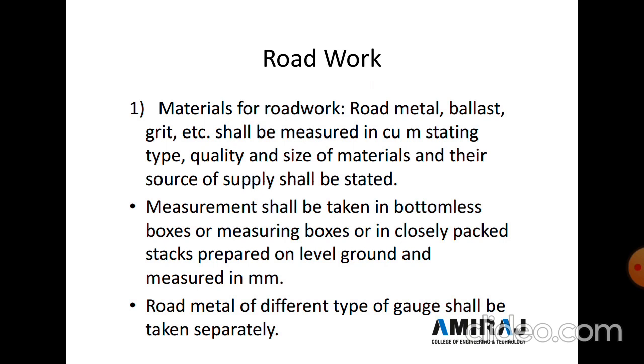Now the next topic we discuss in modes of measurement is road work. Materials for road work, such as road metal, ballast, grit, etc. shall be measured in cubic meters. The type, quality and size of the material and their source of supply shall be stated, and the measurement shall be taken in a bottomless box or a measuring box or in closely packed stacks prepared on a ground level.